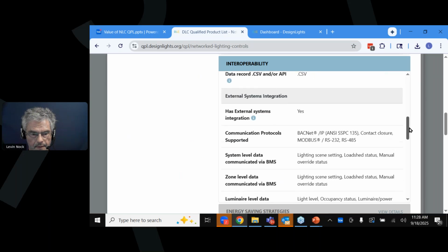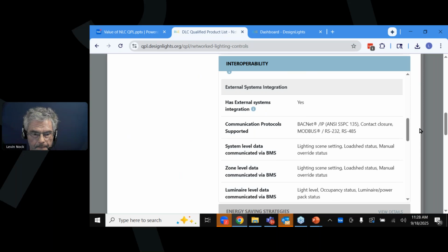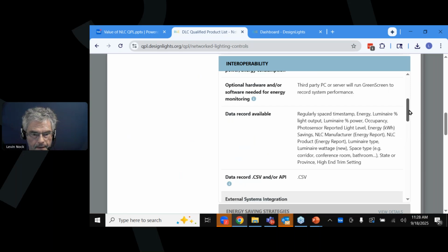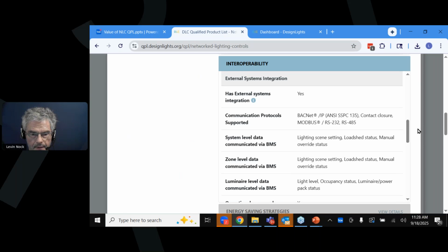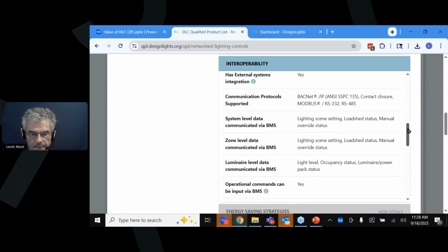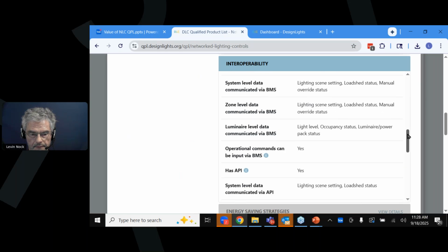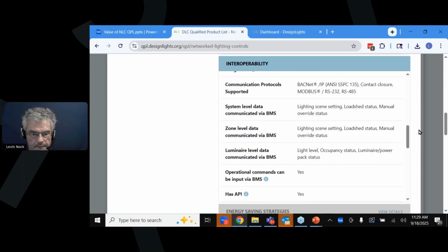So, okay, great. Then I have the communication, like how can I integrate with this system, right? I have a BACnet system, so I can basically integrate with any HVAC system on the market. I see we have Modbus available as well. That gives me some flexibility if we're going to integrate with more traditional electrical infrastructure, or if I'm walking into a more legacy environment. But I also have a lot more options with RS-232. That gives me more local room control, allows me to do shades and AV easily and simply. And then I also have an RS-485 option.